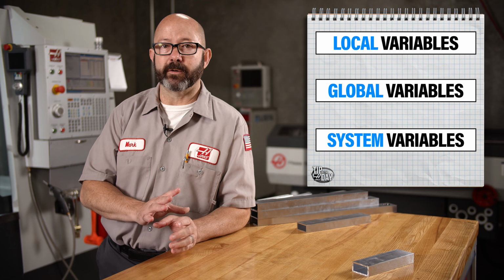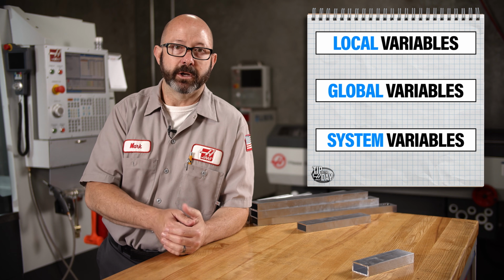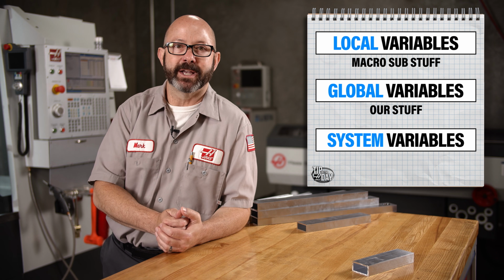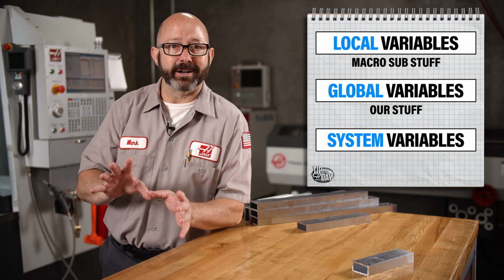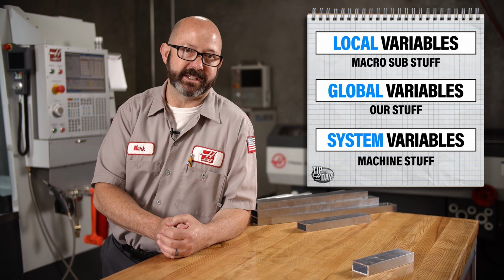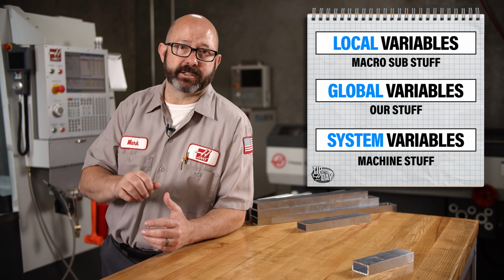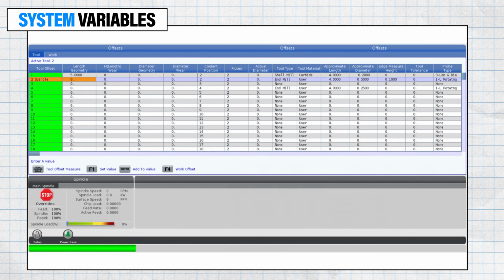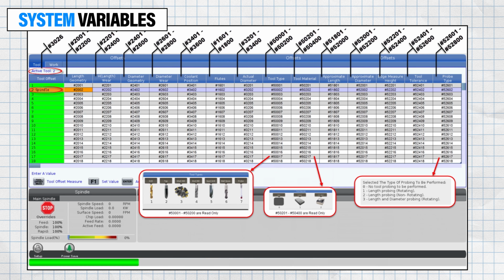Local variables are for macro subprograms. Global variables are for our stuff. We make use of those. System variables are tied to all kinds of machine, program, and system data. That's the machine's stuff, and we can access it. Just about every value on our offset pages has a system variable assigned to it, available for use in our macro calculations.